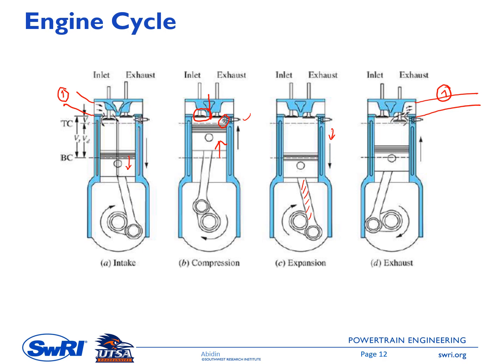So we will see later on there are two sequences of the exhaust process here. First is the exhaust blow down, and this happens when the piston is moving toward bottom center and the exhaust valve opens. Because of the pressure difference, the exhaust gas flows out of the chamber. And the second exhaust process is when the piston moves up toward top center. In this case the exhaust gas exits the chamber because of the piston displacement.